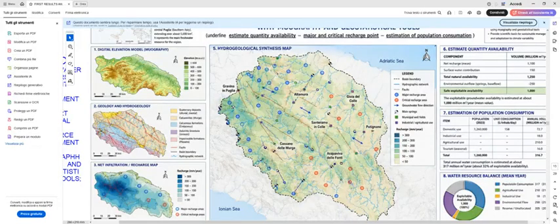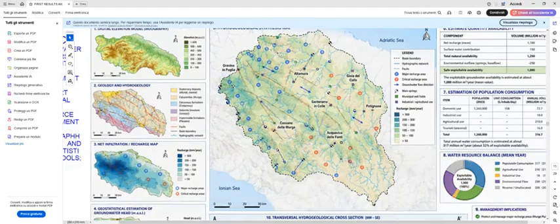The measure flow is in this direction. We have plotted also faults, measure recharge area, critical recharge area, municipal well fields, and you have the net infiltration map. So with this map you underline effectively how much water from rainfall was able to infiltrate the aquifer